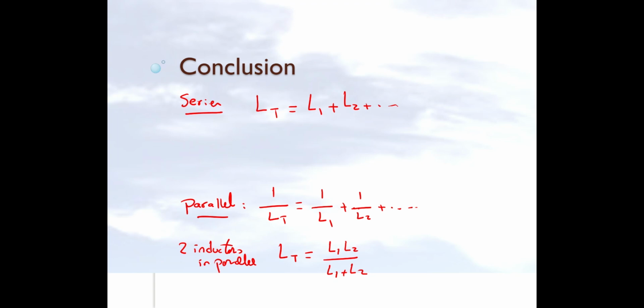Note here that the way we combine inductances is similar to the way that we combine resistors. If they are in series, we add them together. If they are in parallel, we use this inverse equation.